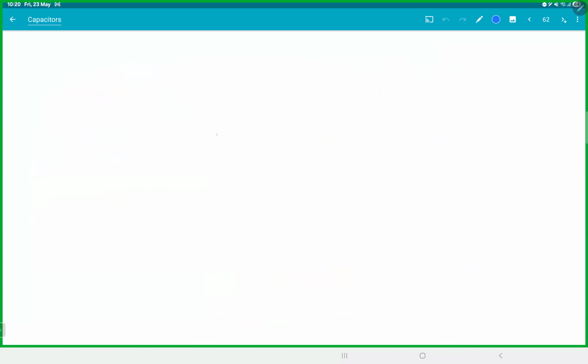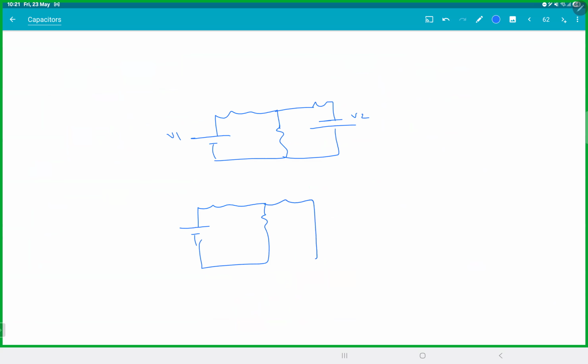This is a very interesting technique. You will later on see, for example, let's say we have a circuit here. Let's put some resistors, a resistor here and a resistor here, and we have a battery like this. Let's say V1 and V2. What you can do is remove the battery V2 and replace it with a wire, then remove the battery V1 and replace it with a wire. Let's say V1 gives you current I1 in this branch and V2 gives current I2 in this branch.